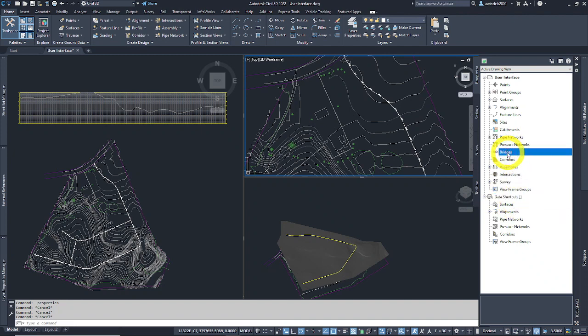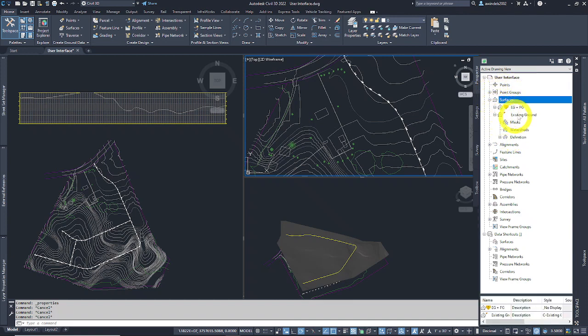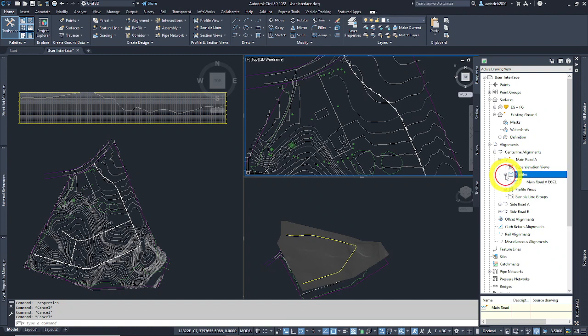A little deeper, but it's related. This is not in the textbook. This is a new add-in in the last few versions of Civil 3D, Bridges. Point clouds are now gone. Those are all part of Recap. But we have all of our areas of Civil 3D. We have a couple Civil 3D entities in here, a couple alignments, as we see as we cascade down. Profiles, profile views, alignments and profiles. Since they're all in this area, that means they're interlinked. They work together. Same with sample lines and later section views.